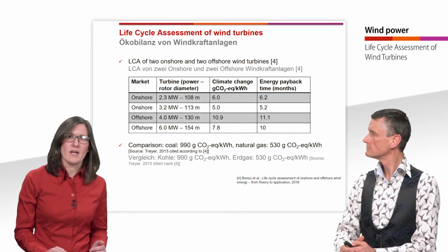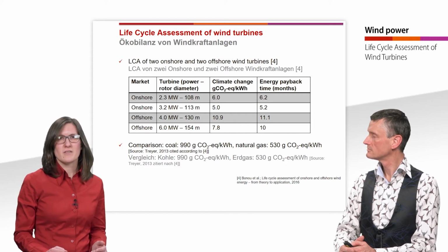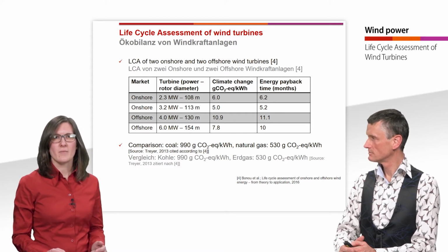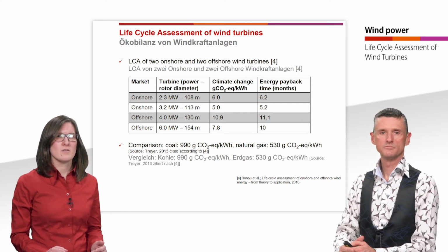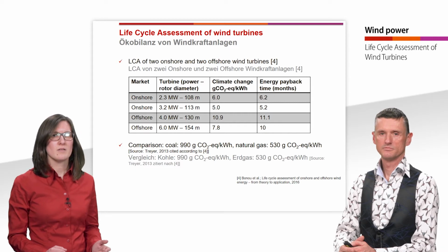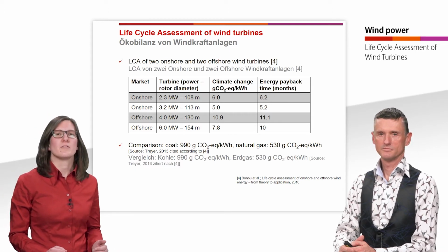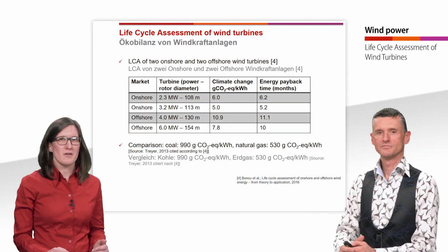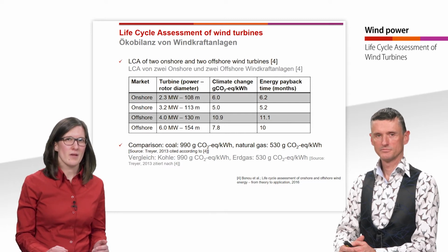And additionally, the table shows the energy payback time. The energy payback time is the amount of time that the system needs to run in order to produce the amount of energy equivalent to the primary energy consumed throughout its lifetime. The values therefore are between 5 and 11 months, thus in all cases lower than 1 year.